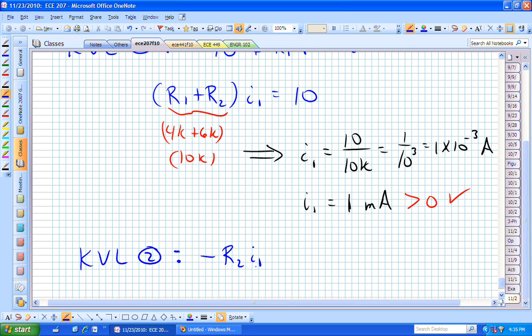Does everybody understand that? And then how did I label V2? It was negative on the left. So I'm entering the negative terminal of it first. I now have minus V sub 2 plus, is that right? I'm now going down the 3-volt source, plus 3 is equal to 0.